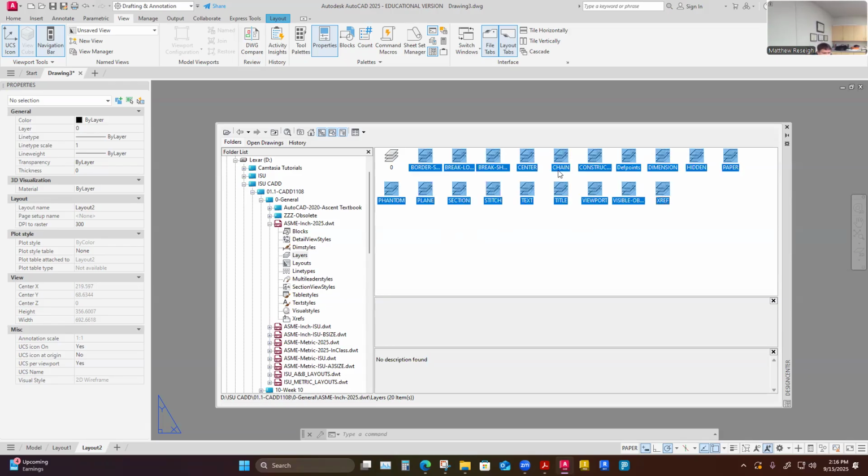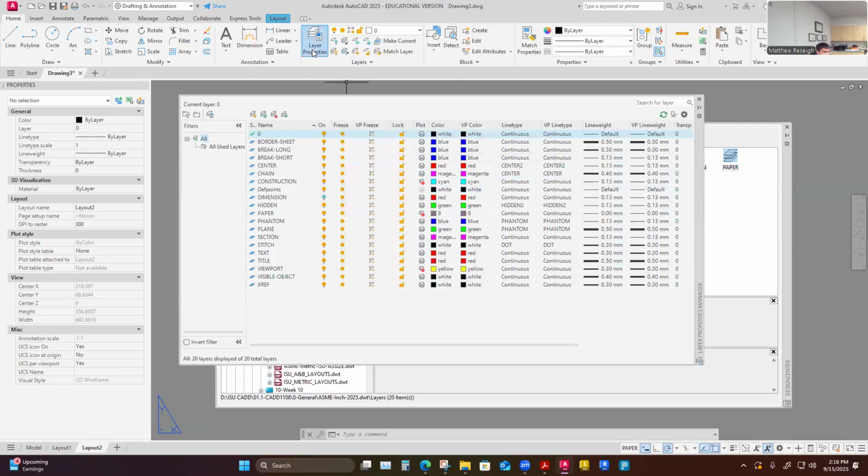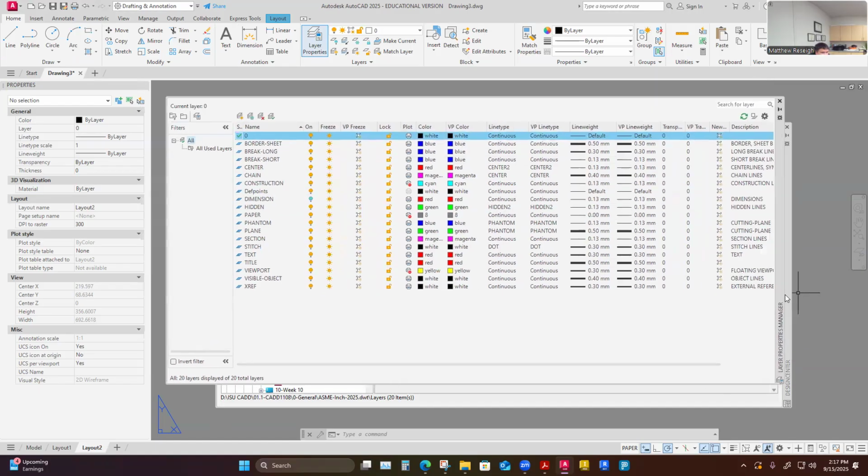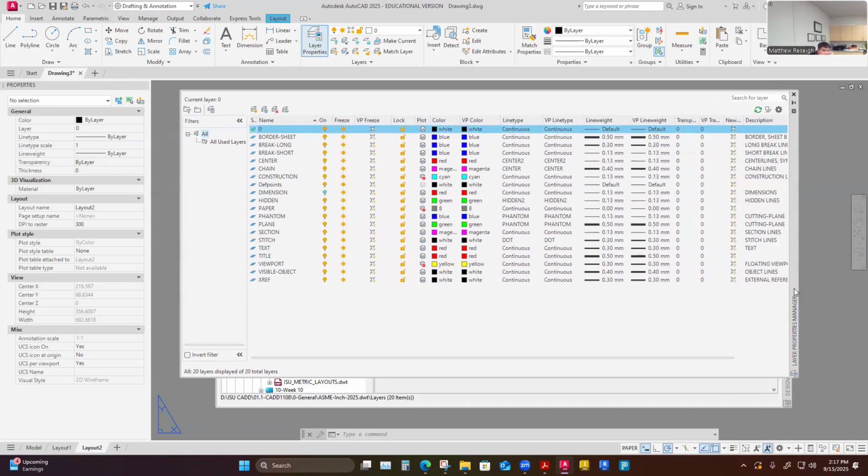What you do is get them all selected and then just drag and drop them right there. I can drop them into kind of my model browser area. I'm in the layout tab, but I can drop them here. Anywhere really, I'm just going to drop them. And then if I check this, they should show up here. So these brought in all my layers that I created. You'll just find the nature of CAD is once you create it, you just reuse it and reuse it and reuse it, as long as it's been created correctly, right?